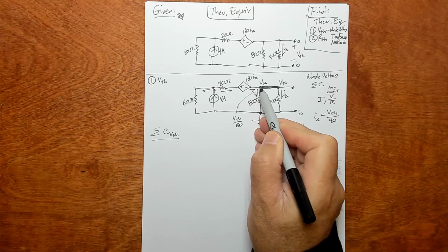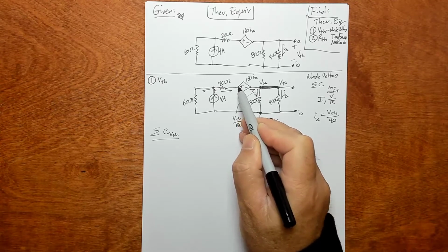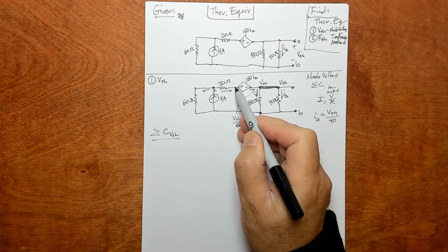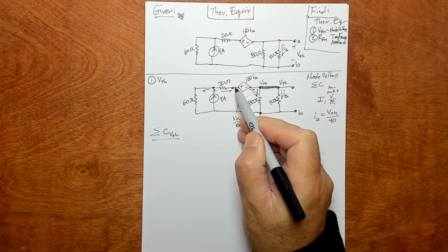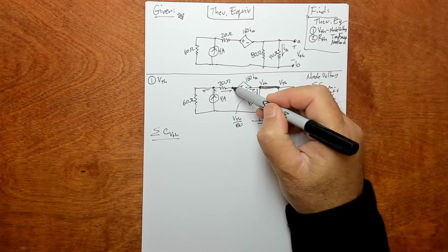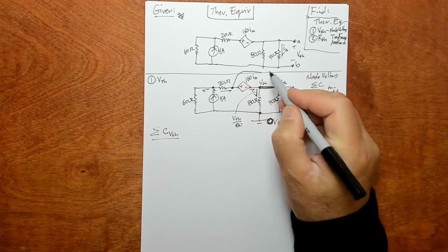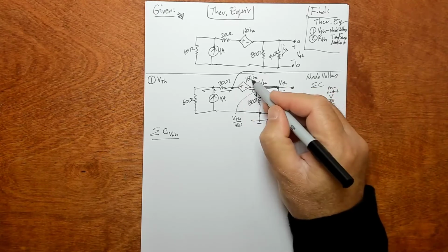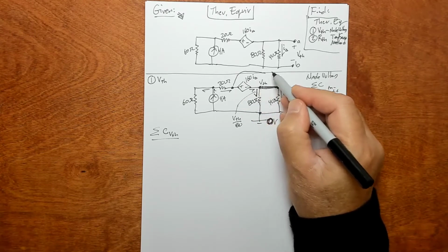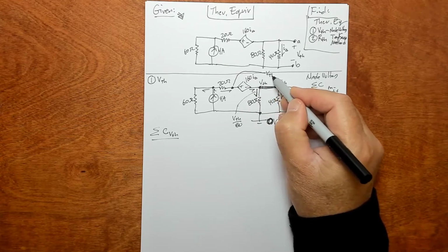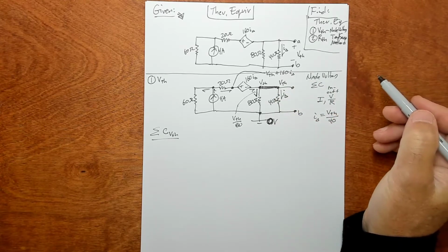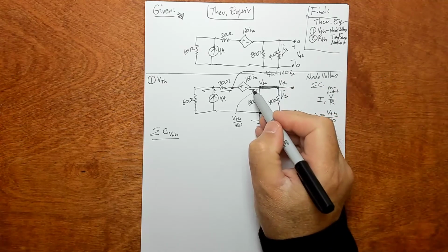So if we were starting here at V Thevenin, the voltage at this point is V Thevenin. And if we go across this device, we're rising in voltage by 160 I delta volts. So that's really what's at this point right here. Let me label this node. We're starting at V Thevenin and going from minus to plus, so we're rising by this 160 I delta. So the voltage at this node is V Thevenin plus 160 I delta. That's what it is.